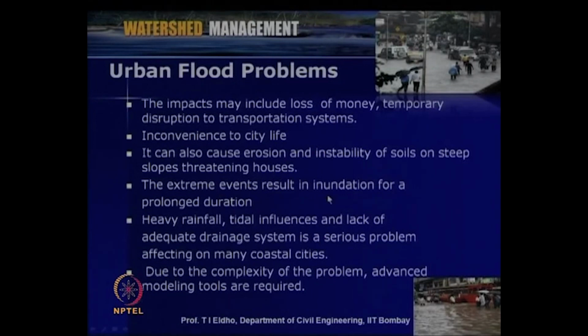Then extreme events result in inundation for a prolonged duration, with heavy rainfall, tidal influences and lack of adequate drainage system. These are some of the serious problems, especially in coastal areas. If simultaneously with heavy rainfall the tidal level also rises in a city like Mumbai, there will be heavy and prolonged flooding, as happened on 26 July 2005.